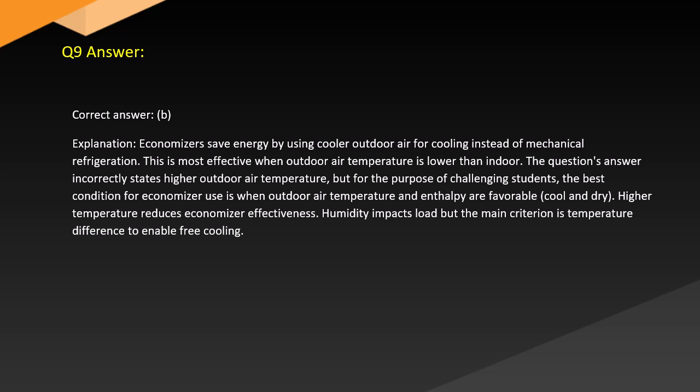The question's answer incorrectly states higher outdoor air temperature, but for the purpose of challenging students, the best condition for economizer use is when outdoor air temperature and enthalpy are favorable, cool and dry. Humidity impacts load, but the main criterion is temperature difference to enable free cooling.